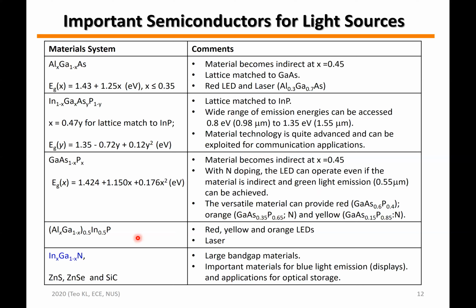Now, the quaternary aluminum gallium indium phosphide is used especially in quantum wells, and the application is especially in traffic lights, where they form the red, yellow and orange LED.